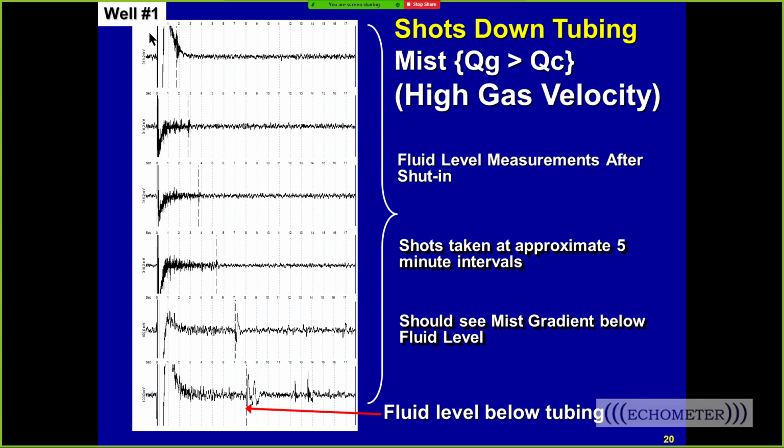That's a common problem. I mean, people in the Utica Shale were doing that. People in South Texas. Every place I've gone, when people are shooting fluid levels, they tend to try to close the well in for a period of time to make it easier to shoot the well, and then they don't understand why it doesn't make any sense. Yes, that also happened with a different company, same North of Mexico, and they knew we were going to shoot some fluid levels, so the operator, for some reason, thought it was a good idea to go and shut in the wells, and then we went like 2 hours later, no fluid in the well. Of course, there were static shots.